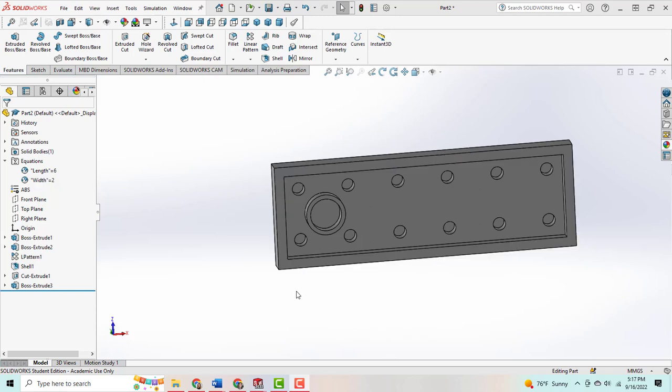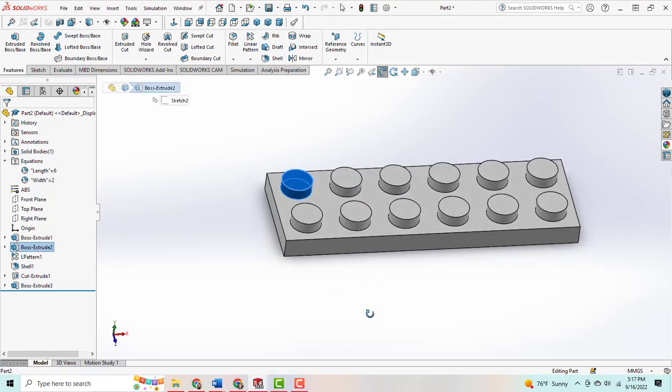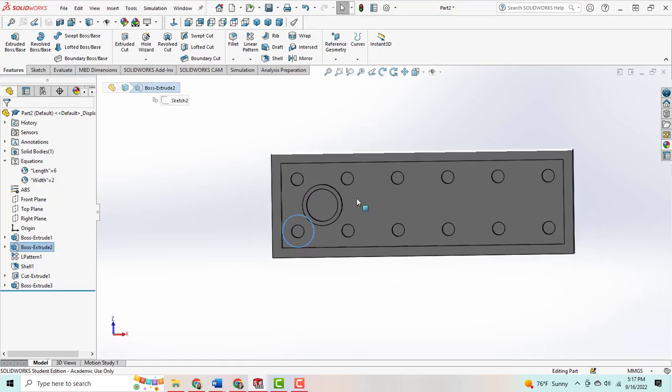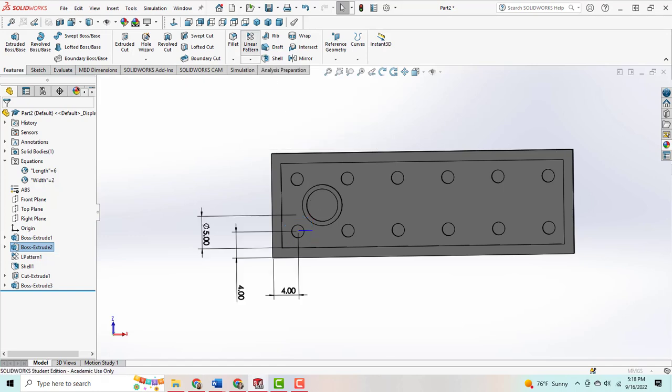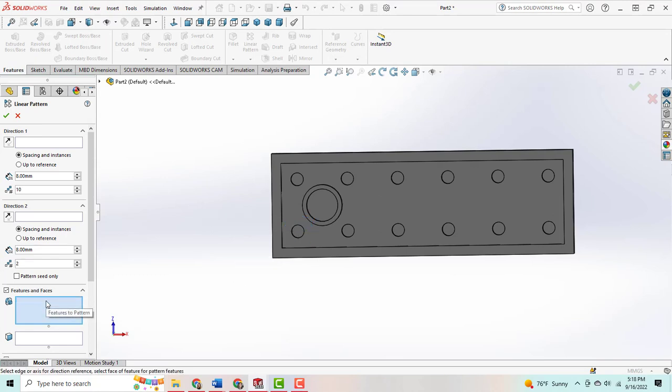Now we are going to create our linear pattern for that bottom extrude. So go ahead and just double check where that first extrude was that you made on your linear pattern for your top knob. Note the side edge and that top edge we selected as we rotate. So now we're going to be selecting the bottom edge and that side edge. So on your Features tab, go to that linear pattern option. We do not want this boss extrude selected.